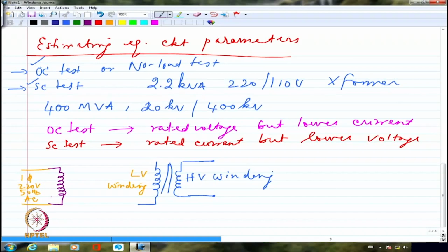Auto transformer is like an inductor, an iron core inductor, nothing else. I just have a larger number of coils wound on an iron core. Now I am applying this entire voltage to that coil. If I tap only half the number of turns, I will get only half the voltage. If I tap 100% of the turns, I will get complete voltage. If I choose only 75% of turns, I will get only 75% voltage. It's as good as a potential divider, but without resistive loss. That's all. I don't have any resistive loss. And it works because of the highly inductive nature of this iron cored coil.